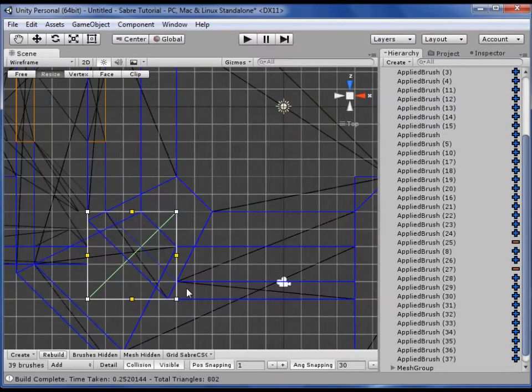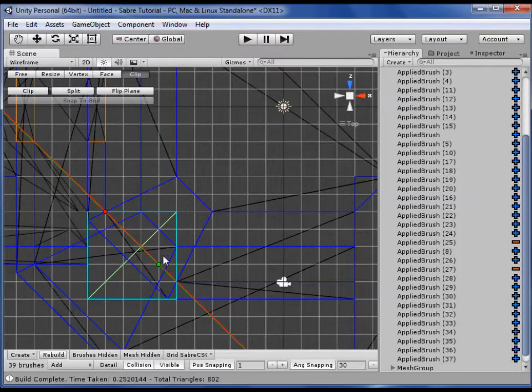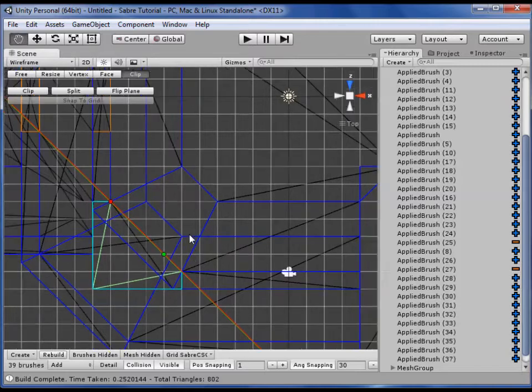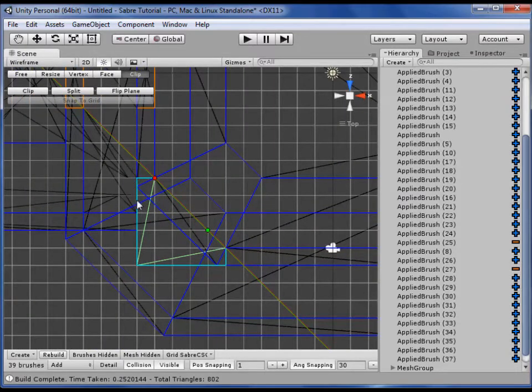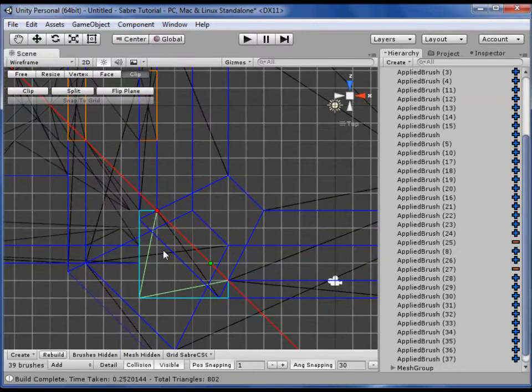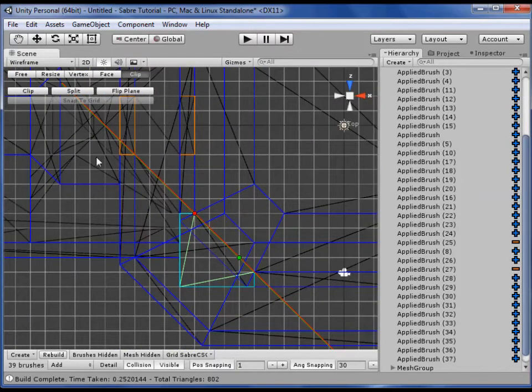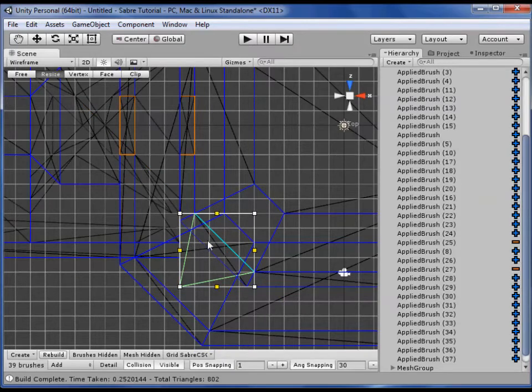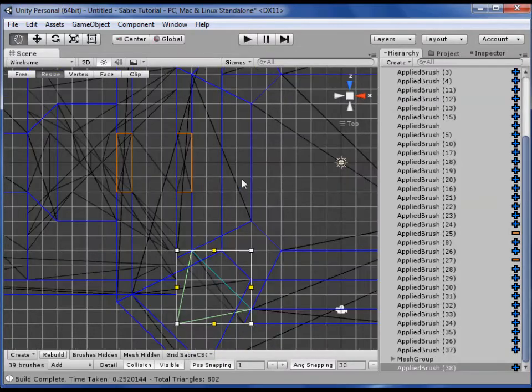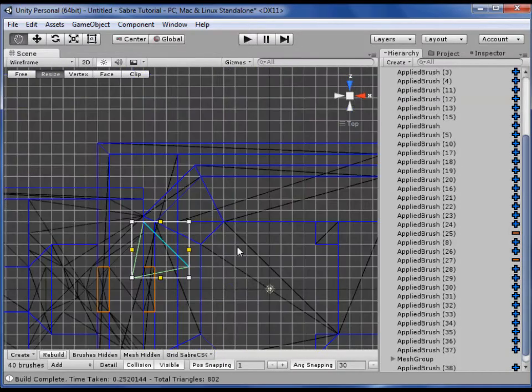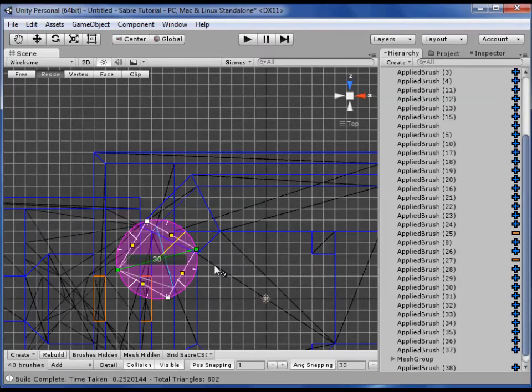And if we see this wall here, this is where the wall that we're trying to replace is originally at. So right now we have this corner sticking out and we want to clip that off. Okay, but now we have a smooth edge here, or rather just flat and aligned with this other wall instead of having the angled edge that we need to deal with. And that should make it easier for us. Let me go ahead and make sure that I deleted the wall behind here. Yep, there we go. And then let's go ahead and duplicate and do the same thing on this side.